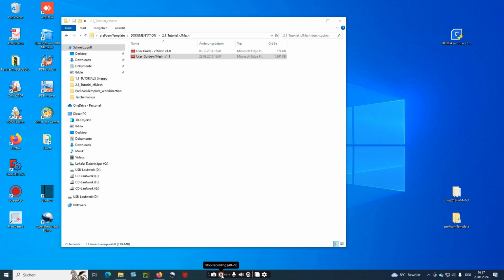Both of these tools create hexahedral dominant meshes, but cfMesh is also able to create tetrahedral or polyhedral meshes. In comparison of these two tools, I would say that Snappy has more control of settings like mesh quality and layer settings, and can also work with cyclic or porous zones. cfMesh in its free version cannot deal with zones or does not create high quality meshes, but in general it is easier to set up because mesh quality and layer creation settings are automatically integrated in the meshDict.